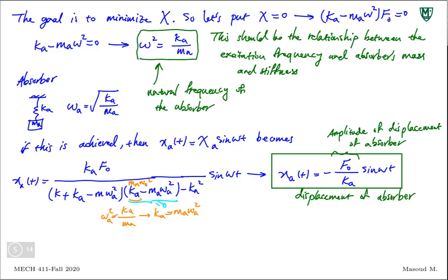Well, the problem is in so many cases you have limited space. Let's say you have 50 centimeters, a meter under the table. You need to find out the displacement of the absorber, or the amplitude of displacement of the absorber, to make sure that this amplitude is not more than the space you have. You put the spring and mass there, and this spring and mass starts oscillating. The absorber oscillates and absorbs the energy from the main system. The higher the energy in the main system, the bigger this amplitude. This mass spring has to go up and down, maybe more with higher amplitude.